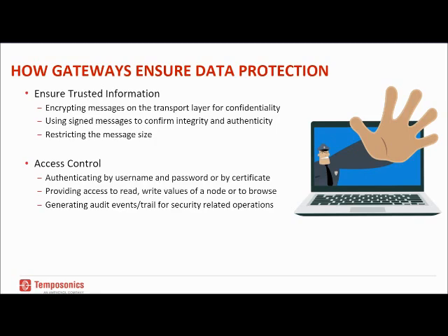In terms of access, there's usually an authentication layer to this. With our gateway we have a username and password right at the front end to gain access to that gateway. And most gateways will have that type at a minimum, username and password, or they'll provide some type of certificate that you have to have on your system to actually use the gateway data. And that data is then provided to you either in read only or write or both, read-write capabilities.